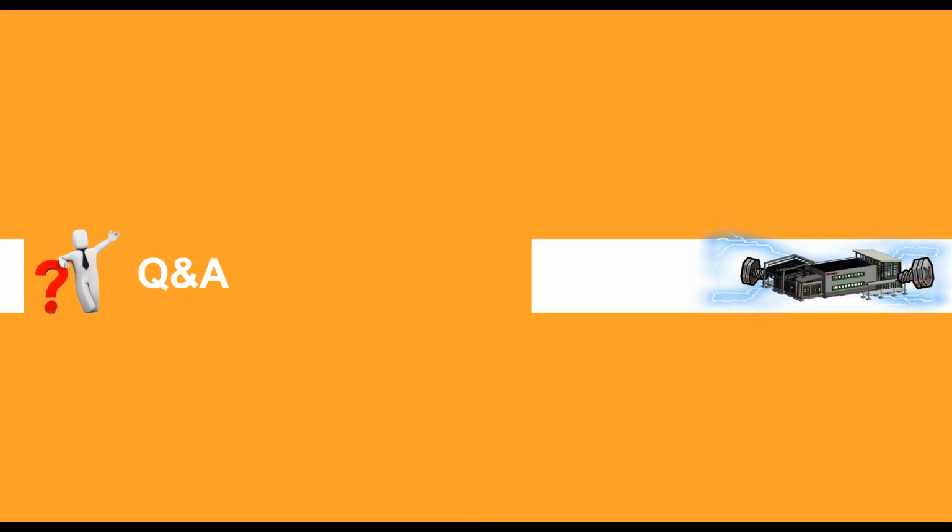Any other questions? What was the path to VR through Live? The path to VR through Live was actually just clicking on the bottom right-hand corner of the screen. It's kind of hard to see because it's trying not to be too obtrusive, but there's a little button down there that actually looks like the figure of a head wearing a headset. You click on that, and if you have your computer set up with one of the desktop VR, so again, the Rift or the Vive, it'll connect to that and send the model into there, and then you can navigate it in virtual reality. So Live and Stingray both will work with virtual reality.